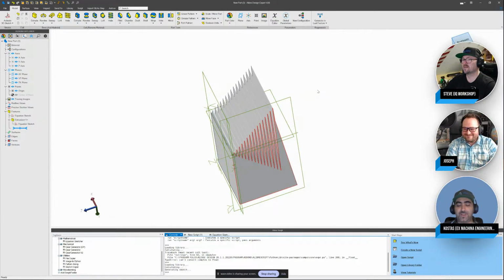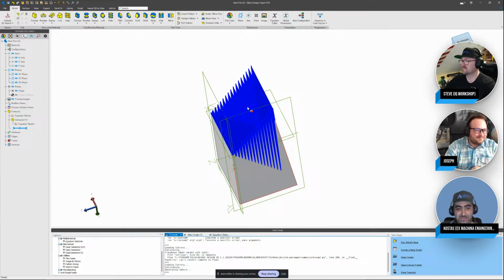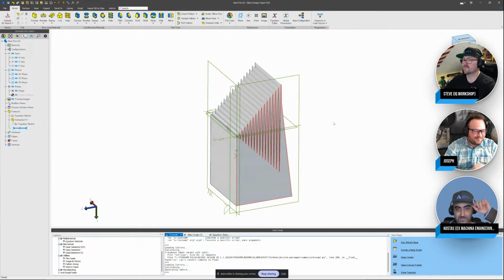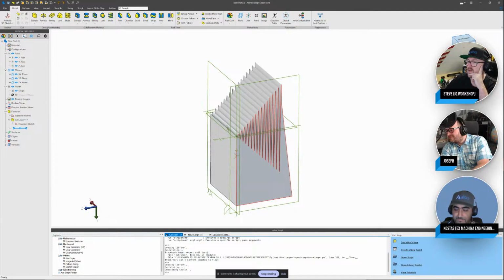So you can do pretty weird stuff, and you can definitely get the third dimension in there going, or control the x direction with one function and the y direction with a second function, which is exactly what you need to draw the involute curve for a spur gear. So you can get that one dimension higher, that equation sketcher, with AI pretty easily, and then you can do some really cool stuff with it. Script in Alibre is really underrated.